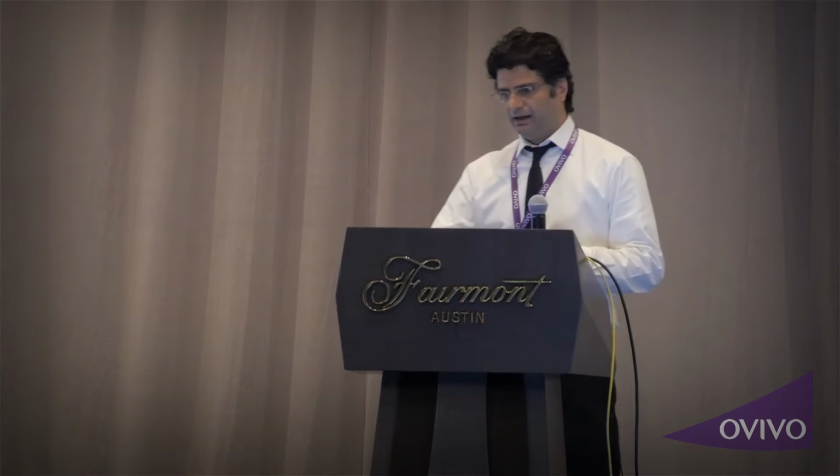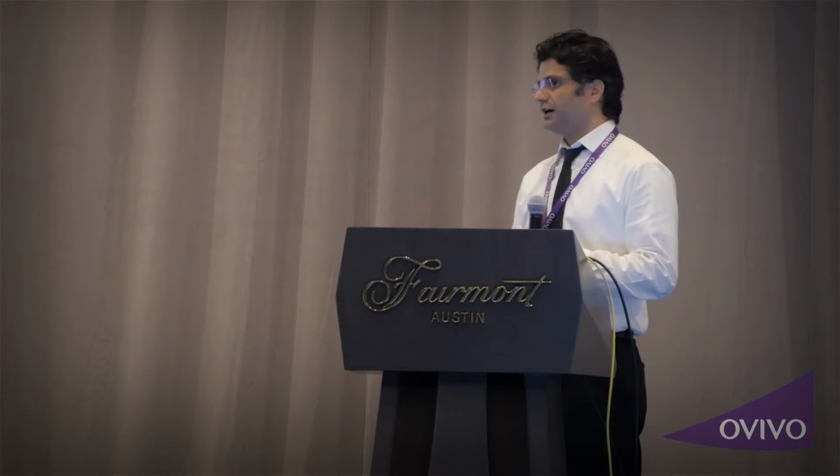So through the data analysis and field observation, we were able to troubleshoot and optimize the system. And in this case, the lack of denitrification was due to high DO in the anoxic basin, improper mixing, and low BOD due to high influent TKN.